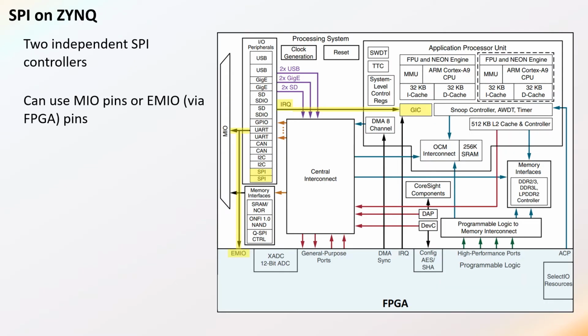Okay, welcome back. This is the second talk on the SPI bus, and this time I'm going to focus a little bit more on the SPI implementation on the Blackboard and Zynq processor. So here is a block diagram of the Zynq showing that the SPI block is one of several I/O processor / peripheral blocks available to the Zynq processor.